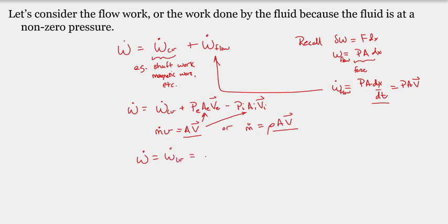And what we now have is that the product of the area times the velocity can now be given by the mass flow rate times the pressure times the specific volume for the conditions at the exit, minus the mass flow rate times the pressure at the inlet times the specific volume at the inlet. Sorry, I dropped a term in here, so let's fix this properly. This is the flow work term only.